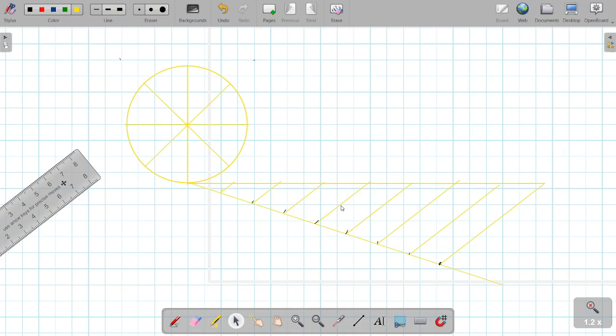Now comes the major part, the part of naming. So in the question it is given that point P is at the extreme left of the circle. So this will become point P now. When this circle is rolling in the clockwise direction, the next point of P will be this. Hence, this will be termed as point number 1 and so on.